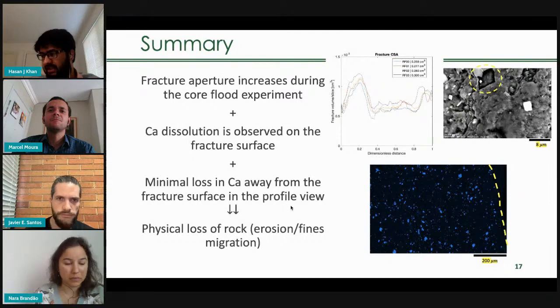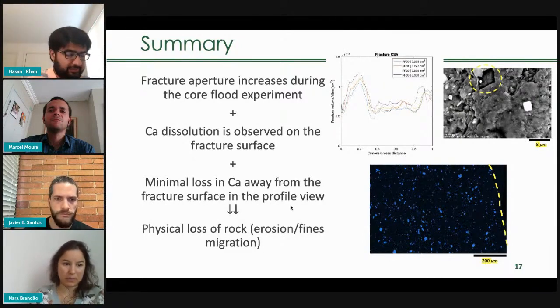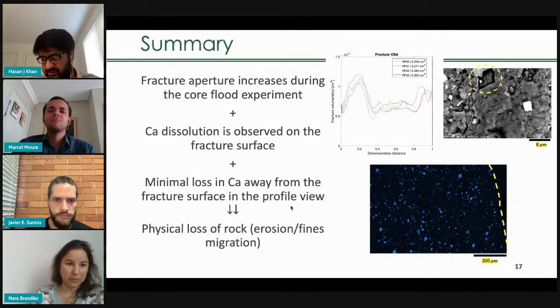So if this case is true, then we would have more issues with regards to the fractures when we're using a produced fluid that has more salt content in it, because if we have a higher salt content, then the dissolution would reduce. If the dissolution reduces, the fractures do not get as big as we are expecting. So that is sort of impeding the fracture growth.